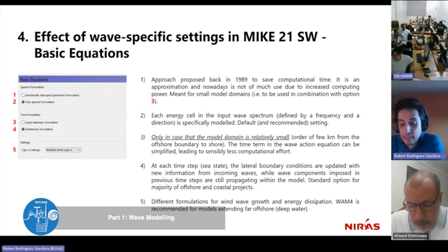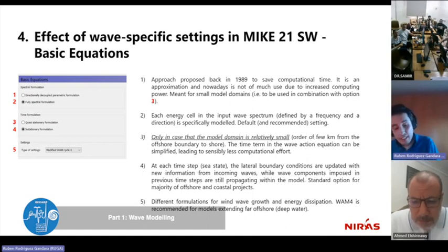that basically covers the whole world, and it tells you how waves generate all over the world just based on the wind. And this formulation, the one that WAM cycle 4 uses, is the most widely accepted and the one that has less bias when compared to measurements, the most reliable one. Maybe if you are working in very, very shallow water, this is not the best formulation. But as a general case, and based on the standard models that are needed in coastal engineering nowadays, I would recommend you to go with WAM cycle 4.